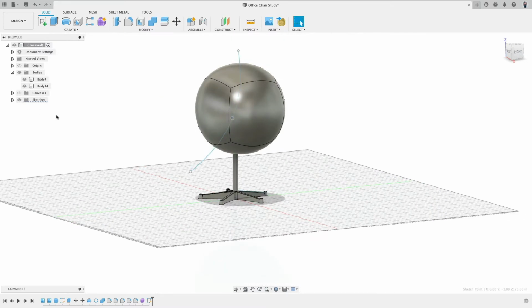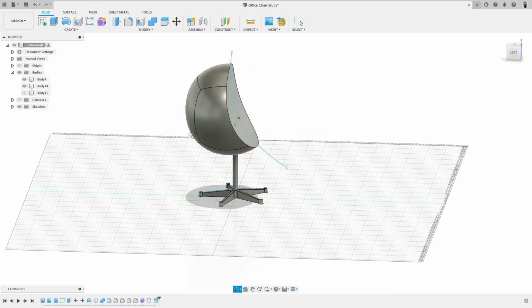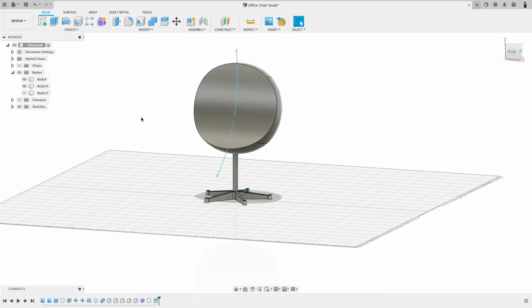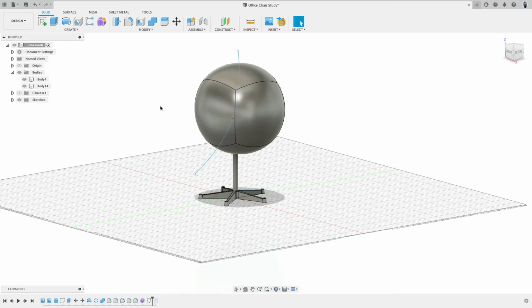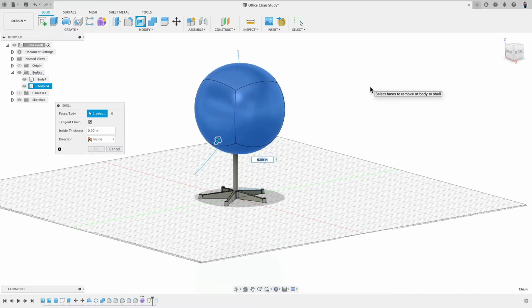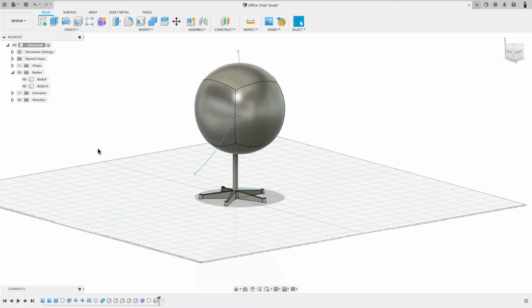So there's now our sketch, and here's our solid block. I can split this body by this line, very good. But yeah, I can't really go in there. How do I open this? Before I do the split, I need to core that thing out. So I go in the timeline back. Here's the shell command. Shell, let's say 2 inches to give this a good material thickness. There we are.